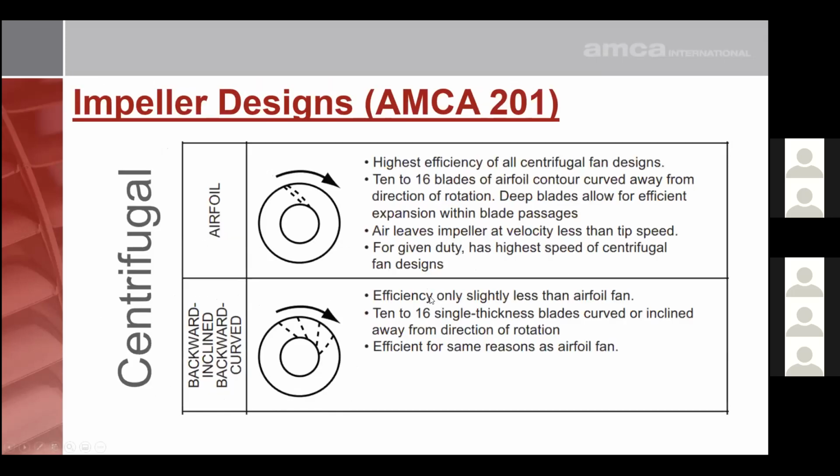All right, so some different impeller designs. We'll start with centrifugal fans, and the most efficient option is an airfoil. There are different shapes, but they try to mimic the airfoil of airplane wings, and they move the air very efficiently. They can be high pressure, but they are better suited for relatively clean flow so that they don't wear unevenly. There's a risk that if it wears unevenly, the impeller is hollow and it can start to fill up with dirt and get imbalanced.